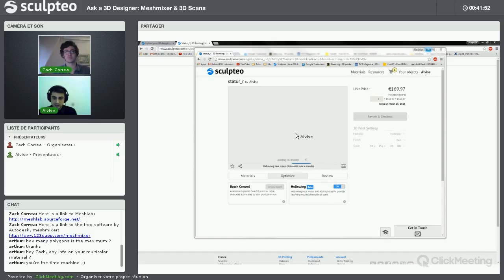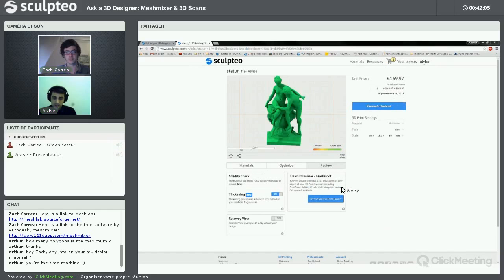So again, you have no parameters to set. The material that you choose is setting everything for you. The required thickness is applied internally, and these two holes were placed by me just with a mouse click on the bottom to make them less visible. The holes are required because we need to remove the powder from the inside of the model. So we physically need two holes to sandblast the model internally. And you don't need to worry about anything else.